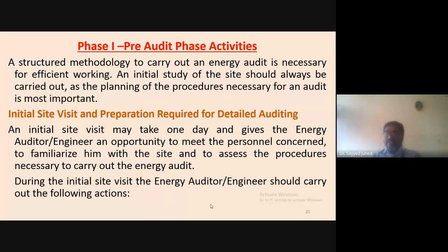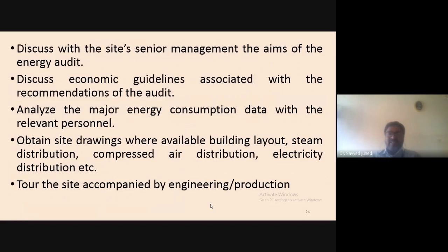This energy auditor should carry out the following actions: discuss with the site senior management the aim of the energy audit, discuss the economic guidelines associated with the recommendations of the audit, analyze the major energy consumption data with the relevant personnel, and obtain the site drawings where available, such as building layout, steam distribution, compressed air distribution, electricity distribution, etc.